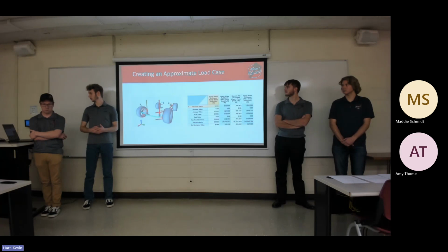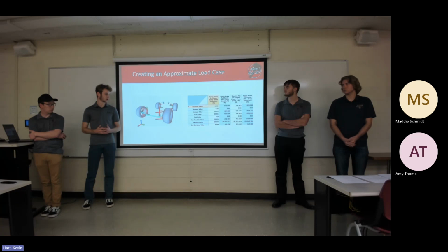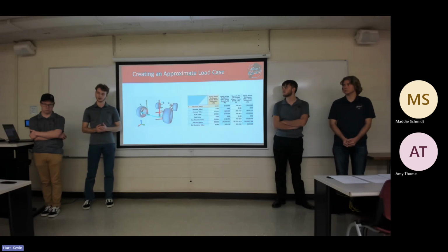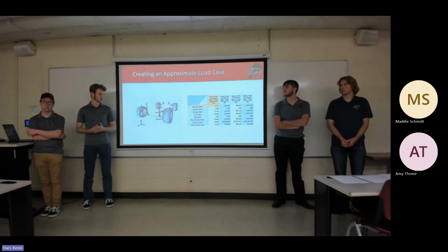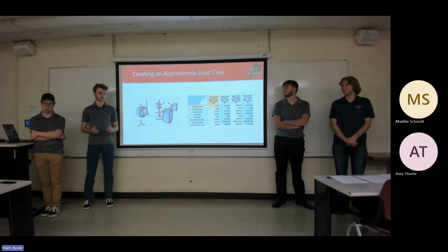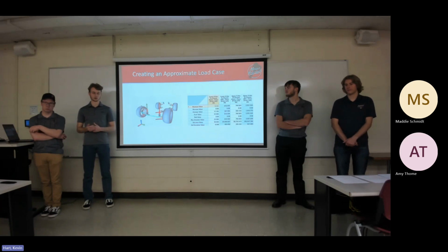So if you move to the next slide, we chose a 500-pound load case, which was somewhat of an arbitrary load case. We considered that the prior weight of the vehicle was about 1,000 pounds with driver in it. So we chose, for a one-wheel load case acting normal to the contact patch of the tire, 500 pounds. And we chose the same track width for our suspension designs to analyze the forces through components such as the control arms and the push rods mainly.